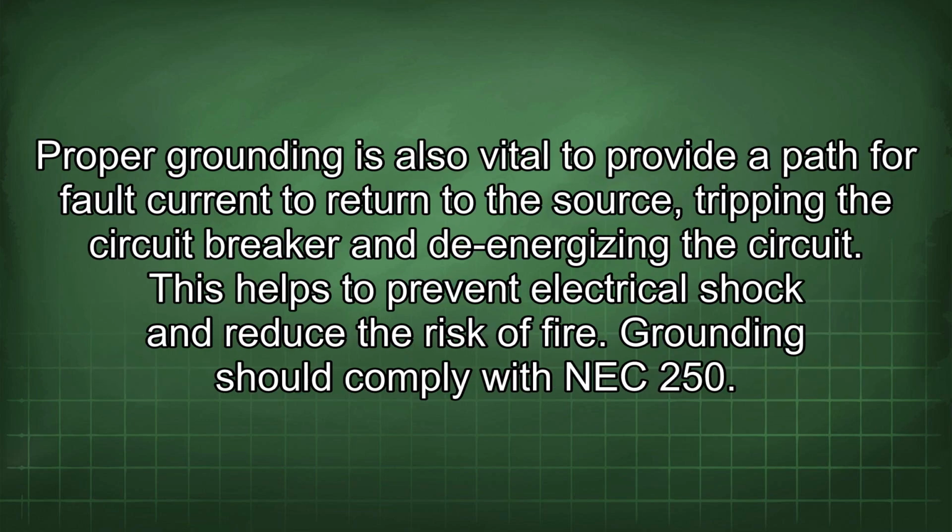Proper grounding is also vital to provide a path for fault current to return to the source, tripping the circuit breaker and de-energizing the circuit. This helps to prevent electrical shock and reduce the risk of fire. Grounding should comply with NEC 250.